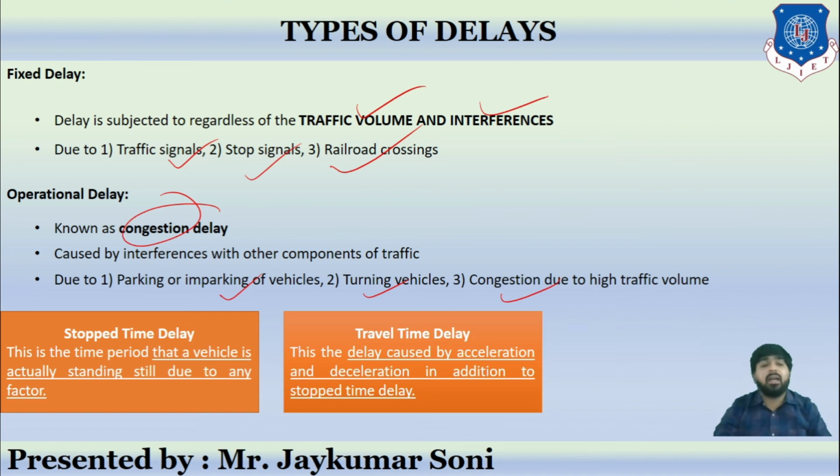Then two other types of delay are there: stop time delay and travel time delay. Stop time delay is the time period that a vehicle is actually standing still. Still means that it is standing. It is not in motion due to any factor. And travel time delay stands for the delay which is caused by acceleration and deceleration in addition to the stop delay.